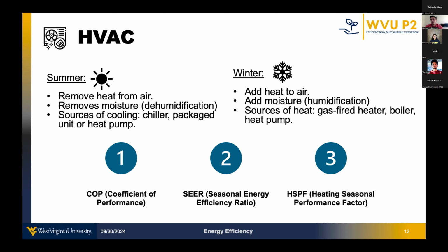On the other hand, during the winter, the focus of HVAC is heating, right? HVAC systems add heat to the air, raising the indoor temperature to a comfortable level. During this process, humidification might also be needed, as heating the air can reduce indoor humidity, leading to dry conditions, and that can affect both comfort and health.